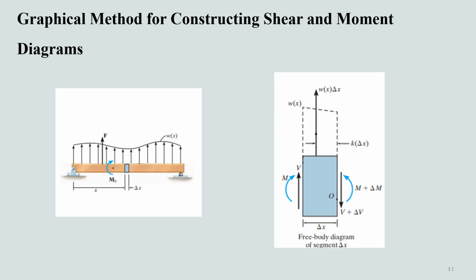In cases where a beam is subjected to several different loadings, determining shear and moment as functions of x and then plotting these equations can become quite tedious. So, in this discussion, we are going to take a look at a simpler method for constructing the shear and moment diagrams, a method that is based on two differential relations, one that exists between the load and shear and the other between shear and moment.